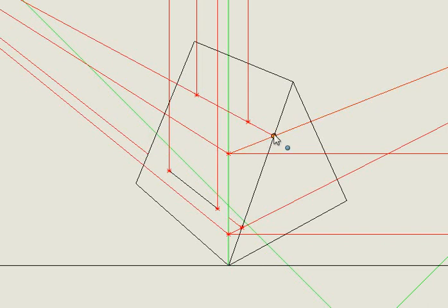Because it's touching this point over here, I'm going to project this point to my left vanishing point all the way. By doing that, I'm also going to be able to touch this slant edge over here. Again, if I run my finger all along this line over here, I'm going to have contact with the slant surface. Alright, so that is exactly what I want. Yet again, I want to be in touch with that slant surface.